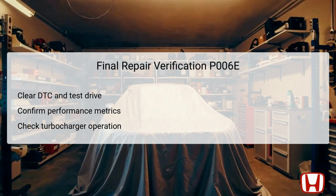After completing the necessary repairs, the final verification step involves clearing the DTC and conducting a test drive to confirm that the issue has been resolved. This process allows the PCM to refresh its memory and rerun diagnostics to see if the DTC reappears.